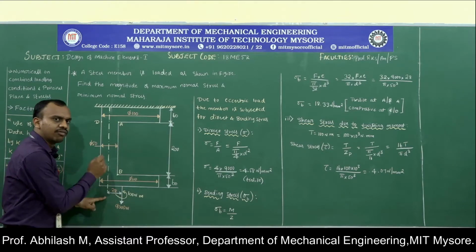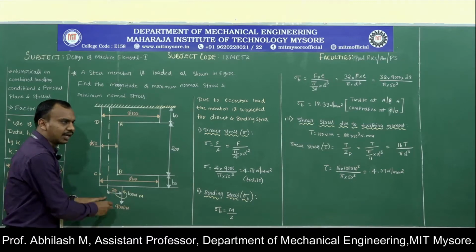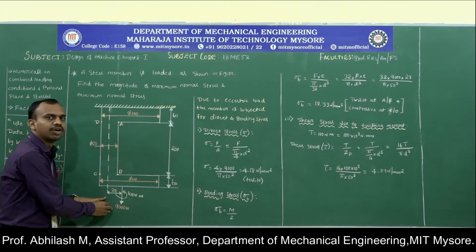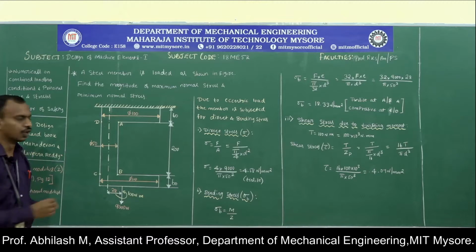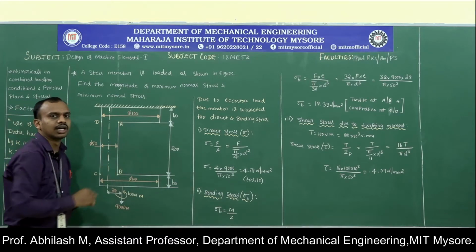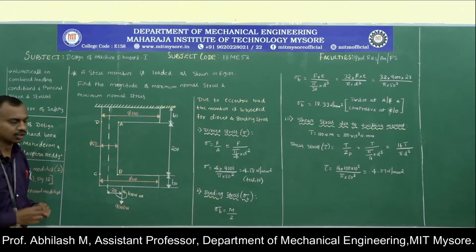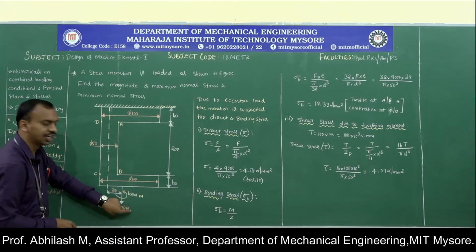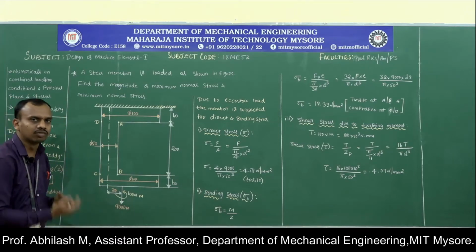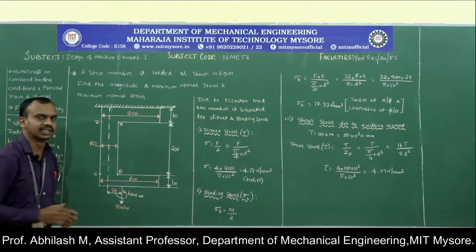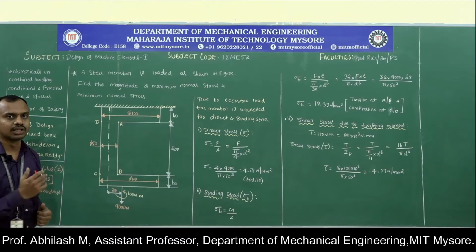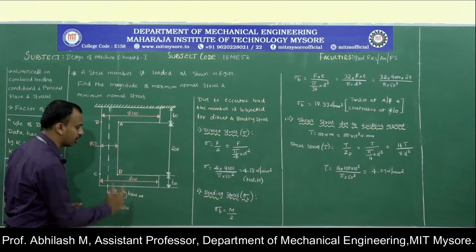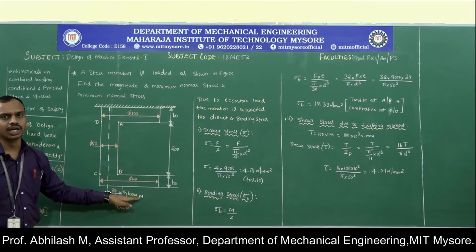If we recall, whenever the axial load is not acting along the centroidal axis of the given member, we call it an eccentric load. So this problem comes under the eccentric loading condition. First, we need to resolve the eccentric load into the direct load along with the couple that is produced because of the eccentric loading. Along with the eccentric load, the steel member is also subjected to a twisting moment of 100 Newton meter.